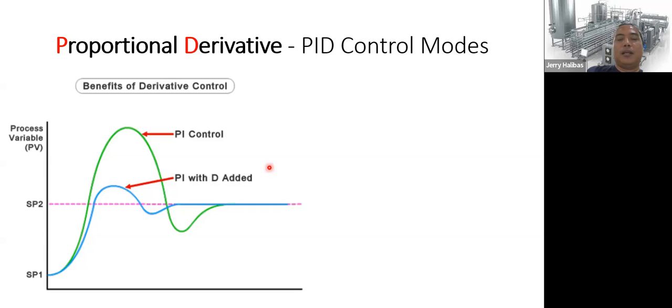instrument. So when you auto-tune your PID controller, sometimes there will be cases where it cannot self-tune or auto-tune the values of P, I, and D accordingly. So sometimes you need to do manual tuning. You set P, then I, then D, so that it does not overshoot while the system is running, to minimize the cases where it becomes unstable.